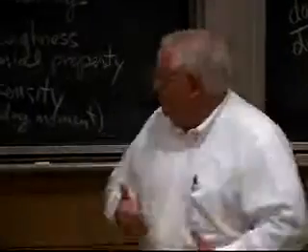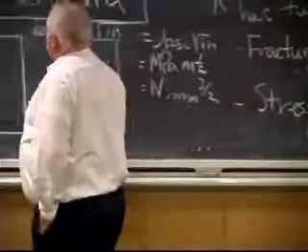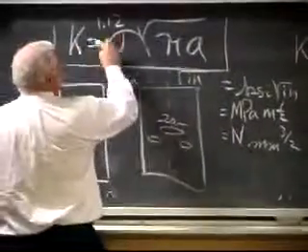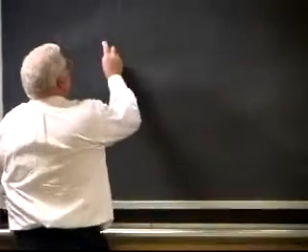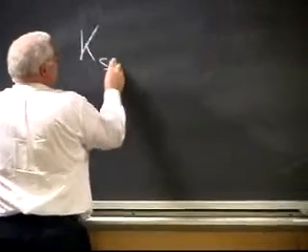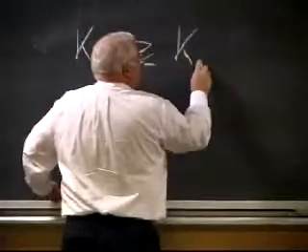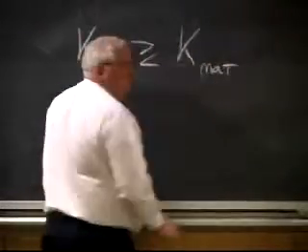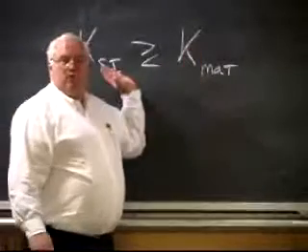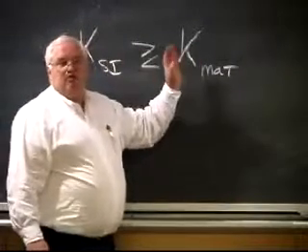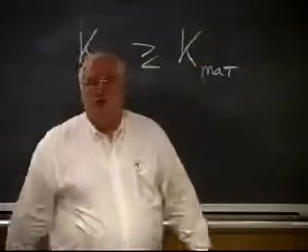And what you're really doing is, if I want to use K as stress intensity, this is the measure of the stress intensity, but whether something will fail is whether K stress intensity is greater than or less than K of the material. Catastrophic failure occurs when the stress intensity gets greater than the material can support. Does that answer your question?